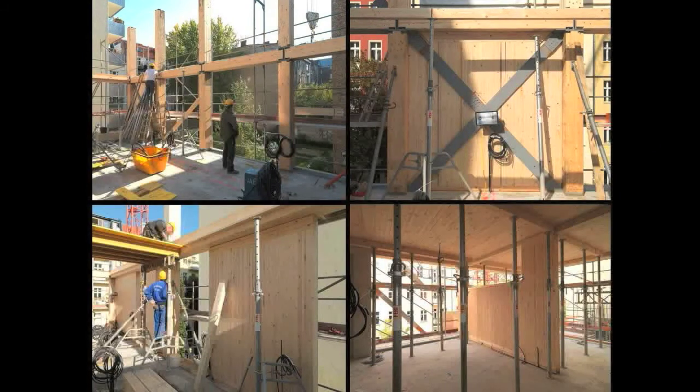I told you we needed only 8 weeks for the construction of the raw construction. That means on Monday and Tuesday they implemented the outer walls with the post and rail construction. In this case, there was no cross-laminated timber, it was only nailed, massive wood, so we needed those Andreas crosses for the stability of the elements.